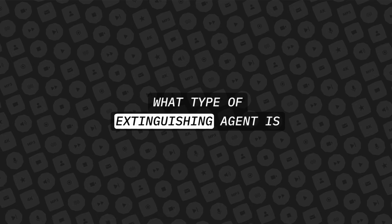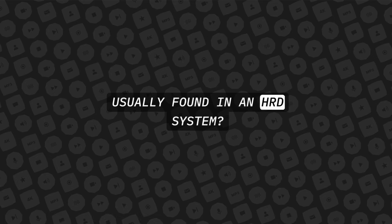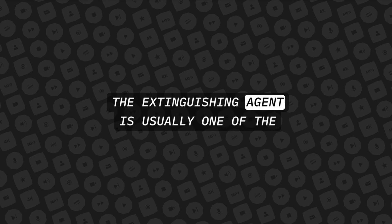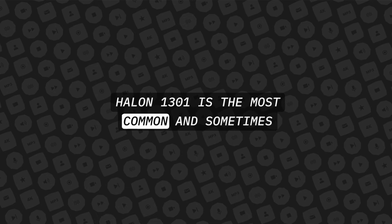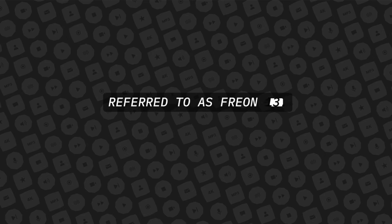What type of extinguishing agent is usually found in an HRD system? The extinguishing agent is usually one of the halons, boosted by high pressure dry nitrogen. Halon 1301 is the most common and sometimes referred to as Freon 13.